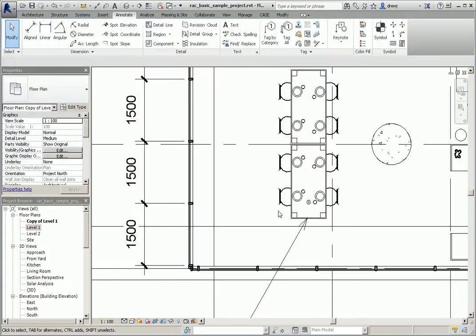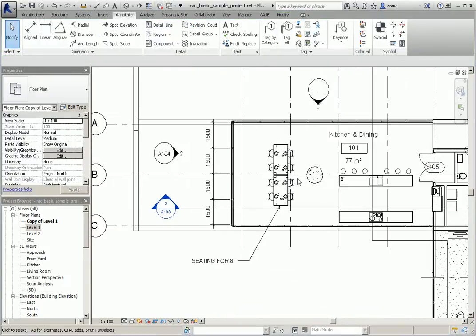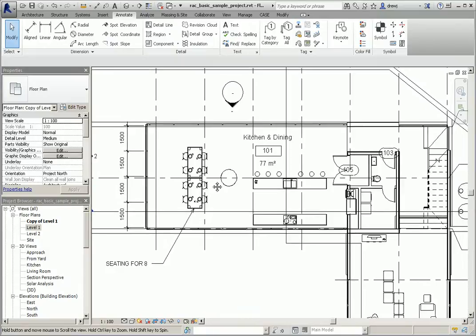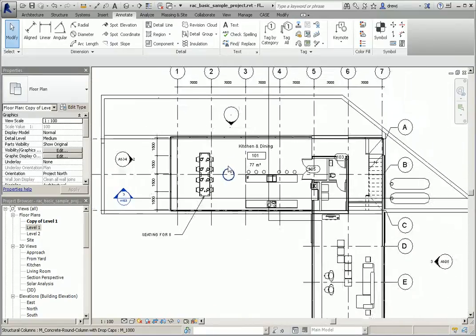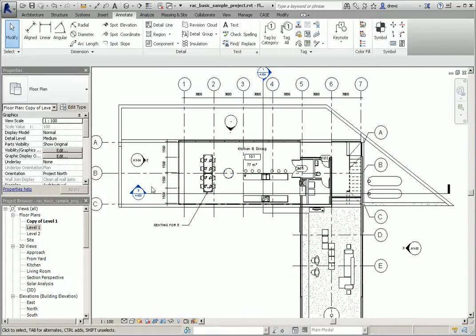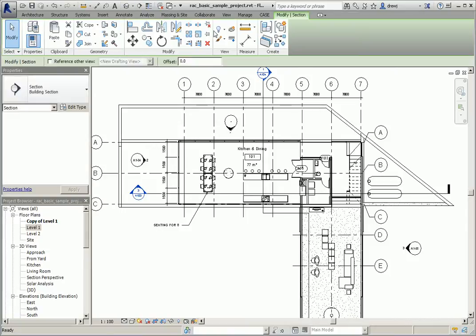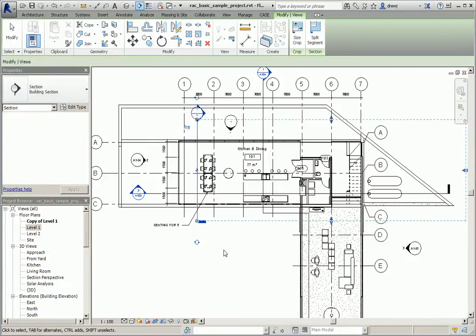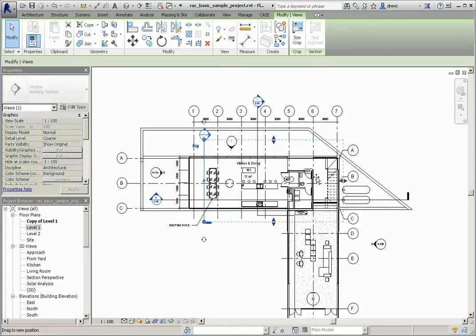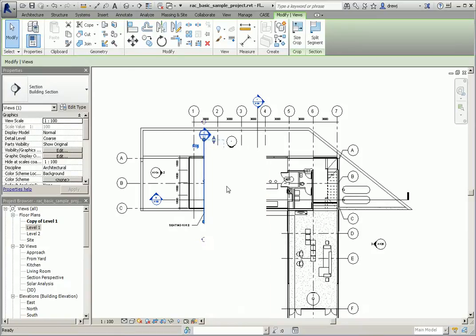Now, one of the great things about having a 3D model is the ability to create additional view directions. So on this model here we actually have a couple of sections, but I'll show you how to make one from scratch. On the View tab, go to the section tool and just click 2 points on the screen. The section has a depth which can be modified very easily, and in order to open a section, simply right click and go to view.